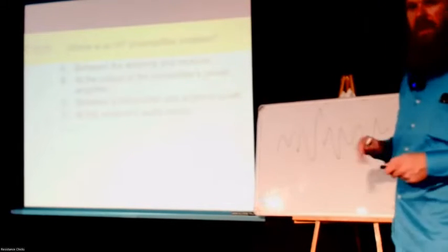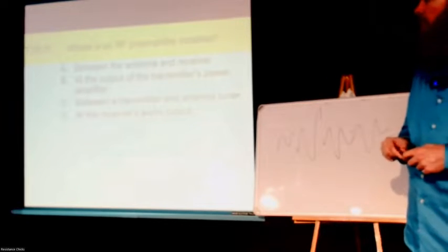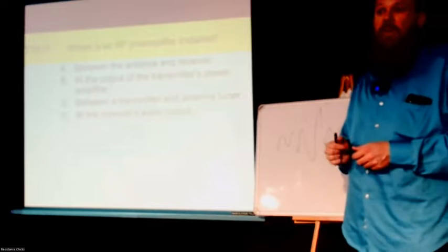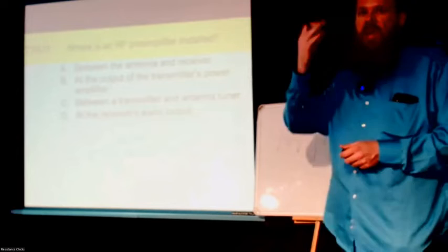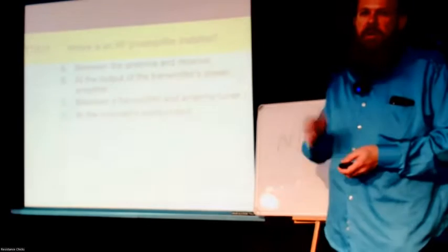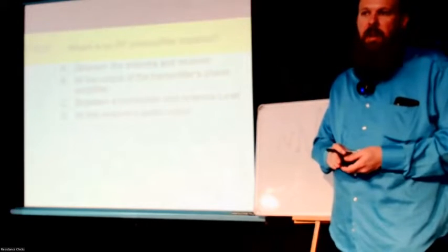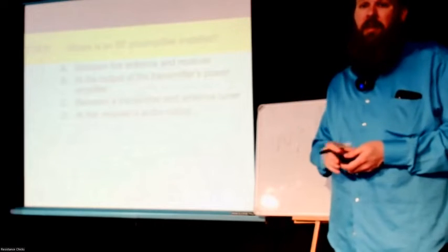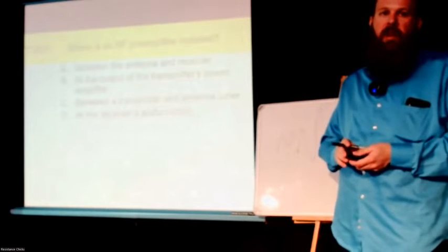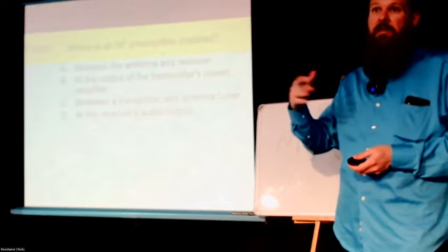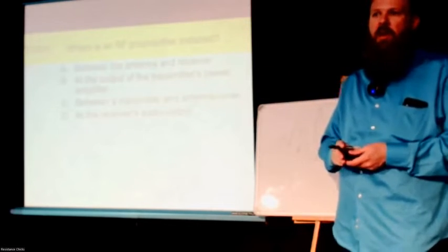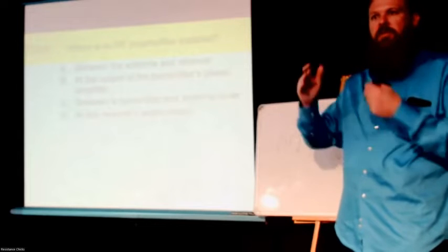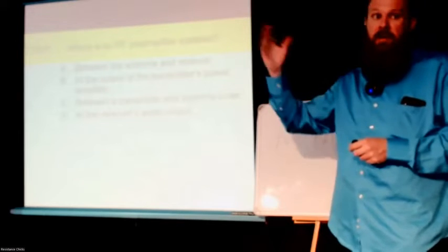It would look something like that, and you'll see it vary as they're speaking. It's a very commonly used piece of test equipment, especially on the audio chain part of the transmitter. As you're feeding the audio in, it is a good way to help you tune the audio to make sure you're not overdriving the radio and that you have enough microphone gain to properly drive the radio. So you want to drive it as hard as you can to its limit, not to exceed it.